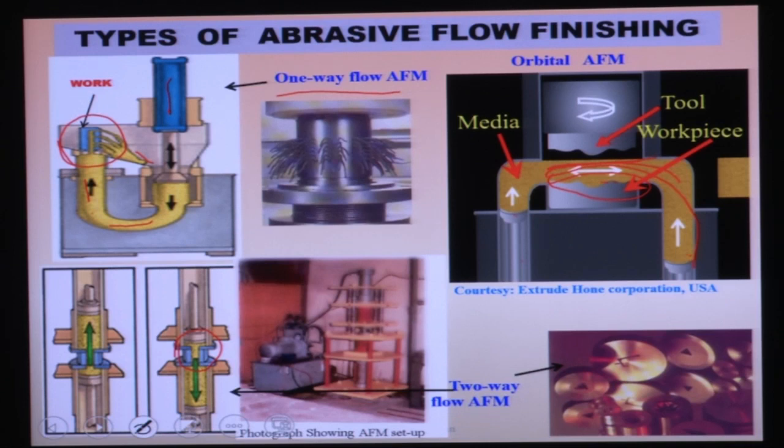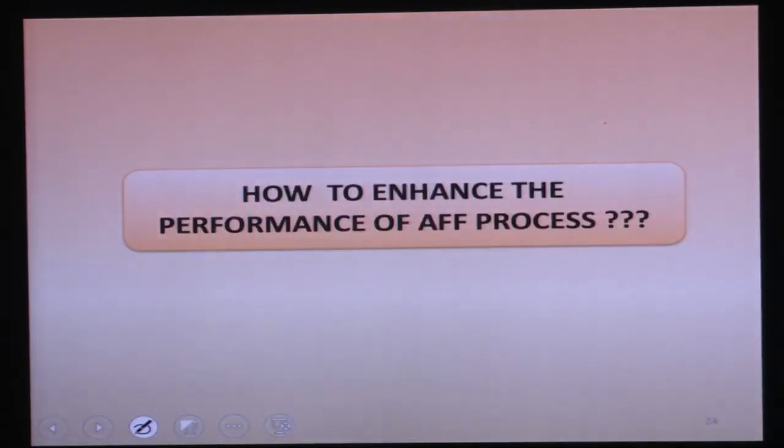And here at the top surface, one tool is rotated. The tool surface is similar to the shape of the workpiece surface, so that uniform pressure can be generated on the media. Okay, so how to enhance the performance of this abrasive finishing process?